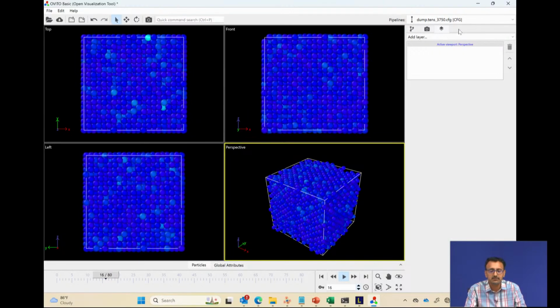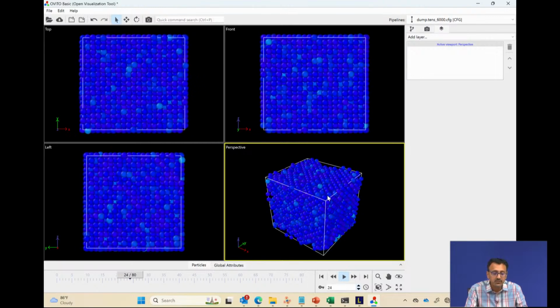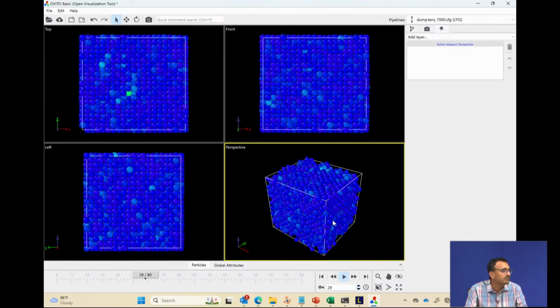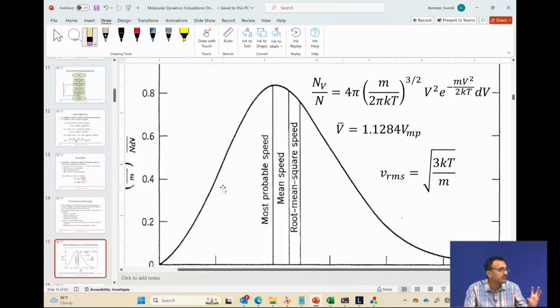Any questions? Where is the dislocation? This centrosymmetry parameter captures the departure from a certain crystalline neighborhood for this system. If the number is 0, it means you are in a bulk crystalline FCC phase for FCC crystals. If it is a different number as it goes beyond 0, that just means that the crystal structure is distorted.